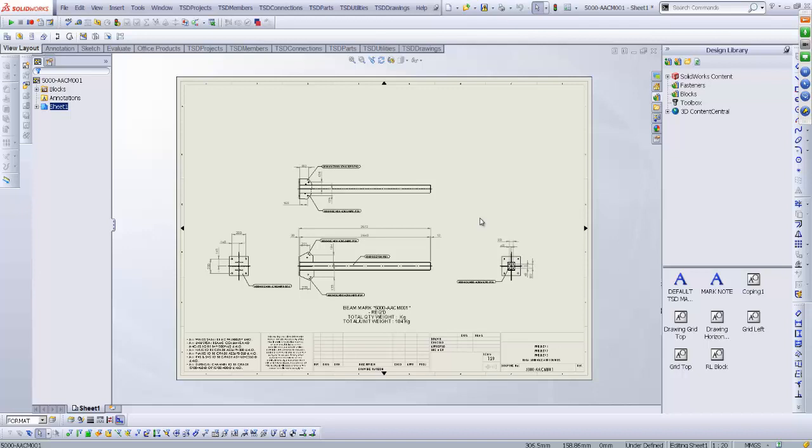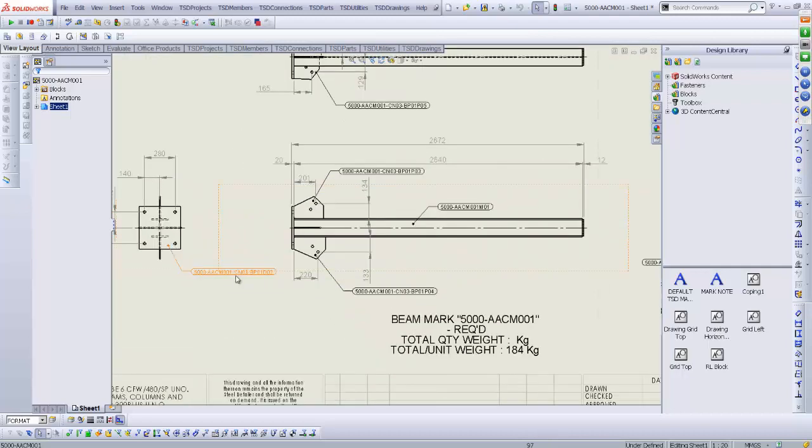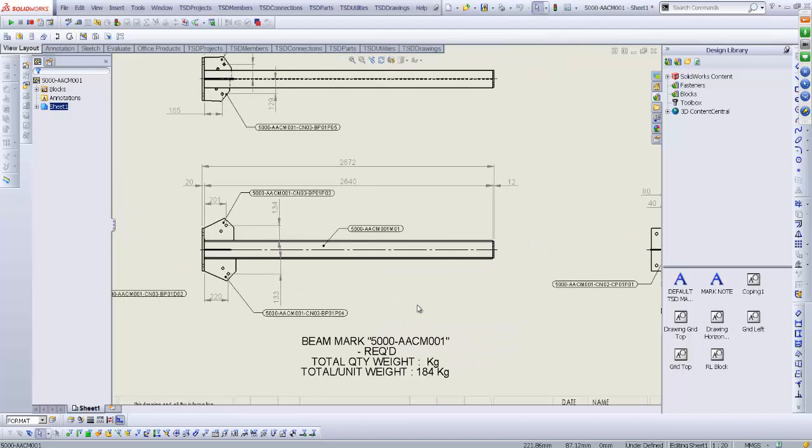Now, you can change those templates quite simply just by going into the library and changing the templates to suit yourself. Now, to do that with mark numbers, we pretty much have to do that if we don't use the stock standard system. So it means that my marking tags that I've got here on all my plates can point to some other custom property. I'm going to show you that also in a second. So at the moment it's set up for defaults.